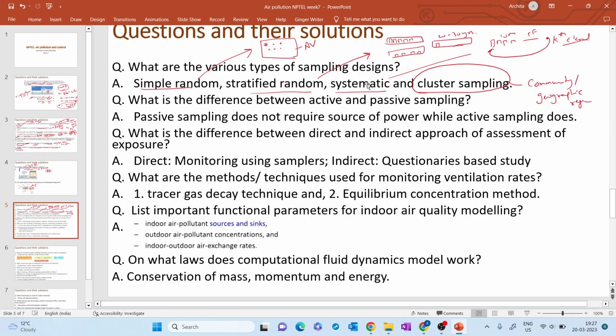In passive sampling you don't have any sense of volume, and you don't have any size selectivity. If I put a tray just beside a highway on a platform, then every particle in the atmosphere, irrespective of size, if it has a density or by the effect of gravity has to settle, it will settle. So size selectivity is reduced in passive sampling.